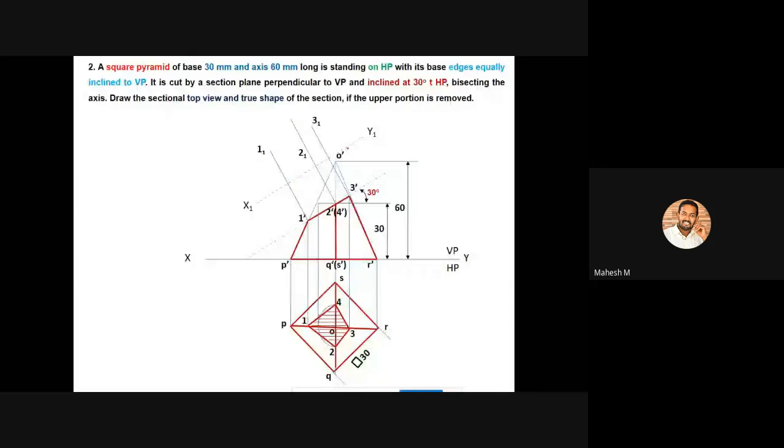Then you can connect all these 4 points with a dark line. And also you have to create the section, or else it can be called hatching, with a 2H pencil. You have to use only a 2H pencil for creating the hatching. The procedure for creating the sectional lines is that you have to follow the 2 mm distance, and also the angle for these lines should be 45 degrees.